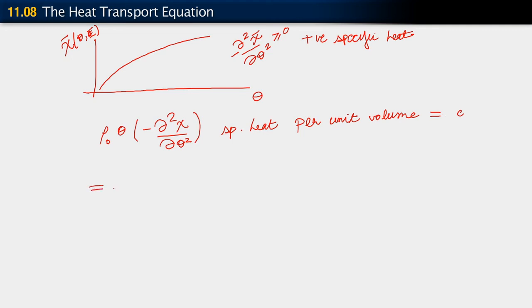Okay, so what this then tells us is that now we have C d theta dt equals rho 0 r bar, temperature rise from heating, local heating, minus J divergence of Q, temperature rise from local heat influx into a little volume, plus, okay, rho 0 theta, second derivative of chi bar with respect to theta and E, contracted with E dot. Okay,